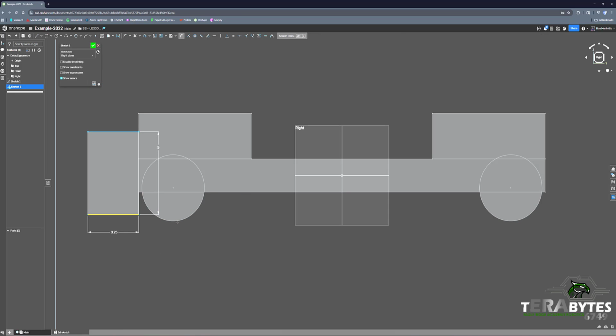Generally, as teams get further and further on, and they start to use over the bumper intakes more and more, they're going to find that when you have a very flat field that you're playing on, you're going to want your bumpers closer to the ground, so there's less of a chance of things getting picked up underneath it. Good examples could be game pieces, especially thinner ones that you might not want to get under your robot. Other examples are other random elements on the field you want to avoid. And it also gives a little more stability by lowering the center of gravity of your robot a bit, by lowering how far down the bumpers are.